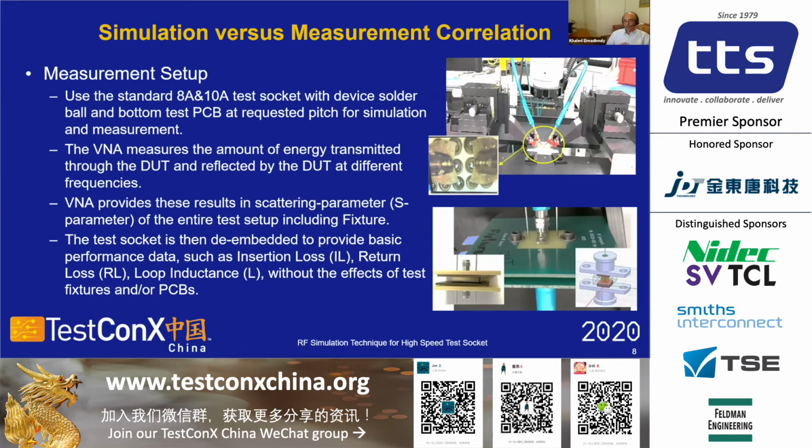And usually the PCB material can change impedance in terms of half an ohm to 1 ohm between one material and another. So it's not going to be a very big difference, but it will improve the result by knowing exactly what material is being used in the board.